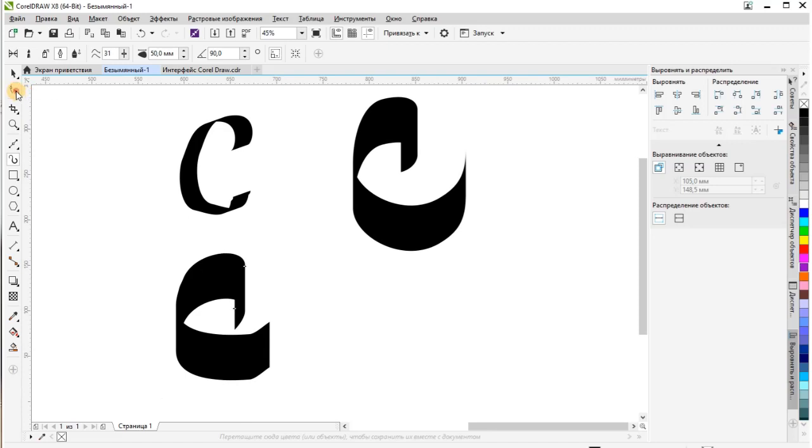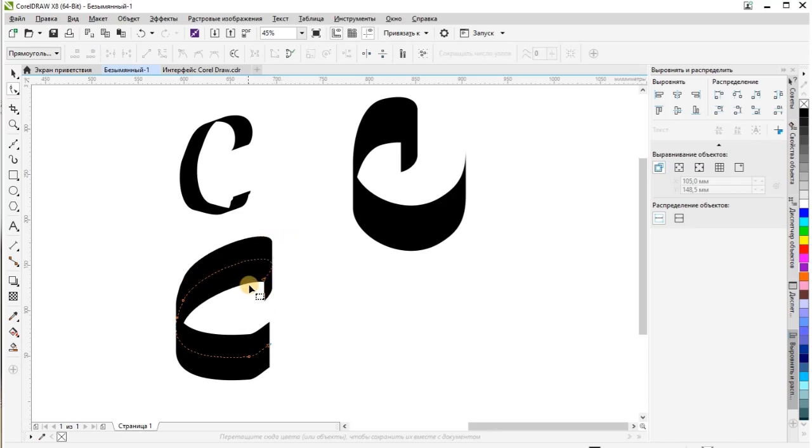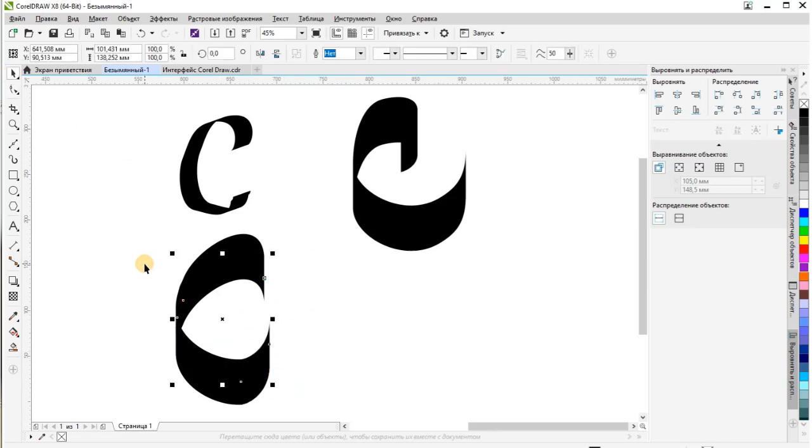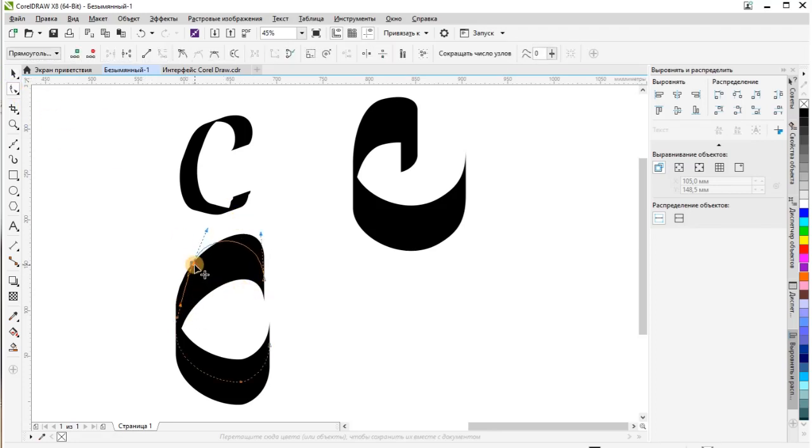The midpoint of a calligraphic pen of a given width and with a given slope to the horizon is set to the start node of the control line, and then moves along it while maintaining the slope. A subordinate object is a closed curve made up of paths formed at the start and end positions of the pen and the paths along which its edges moved.